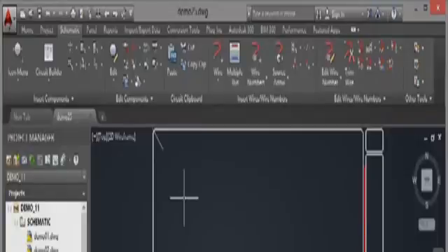Now what you can do is you can set up grids on your AutoCAD electrical drawings, and you can do that by way of controlling the drawing properties. So you would have noticed when we went to insert a ladder on the schematic tab in the insert wires wire numbers panel here, that we have the option of an XY grid setup or an X zones setup.